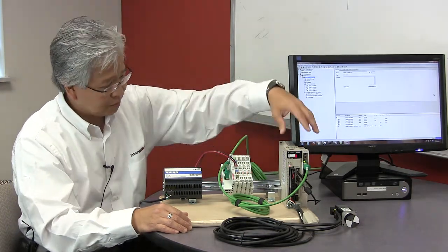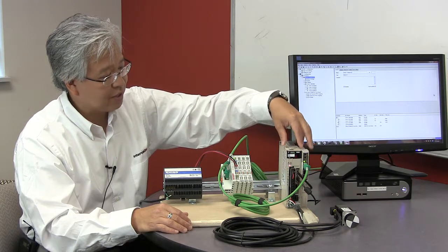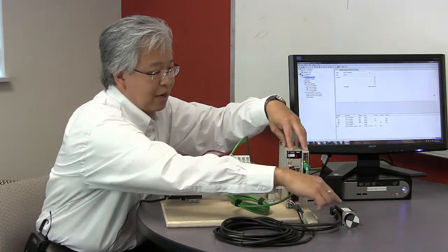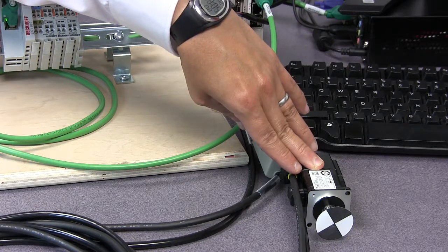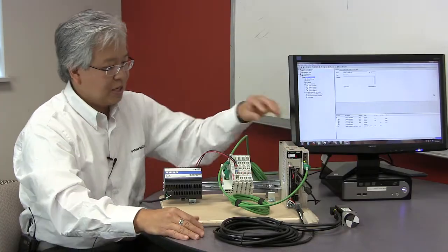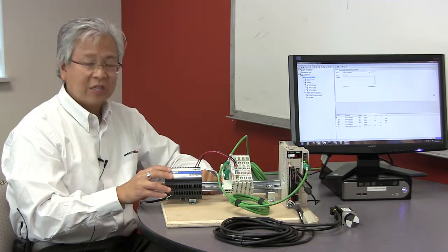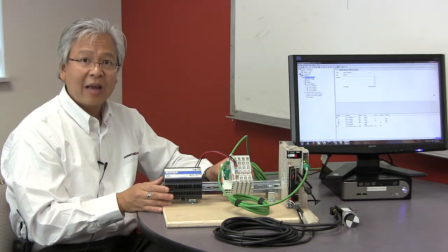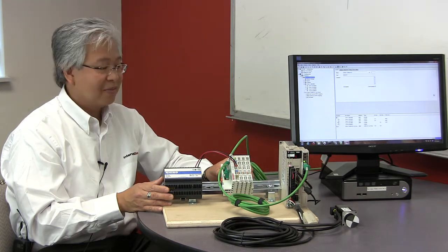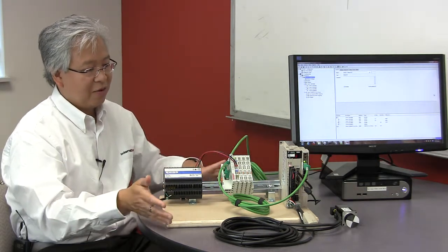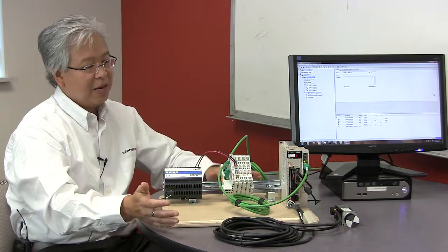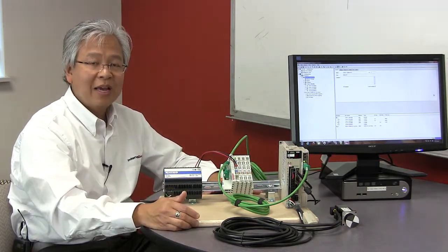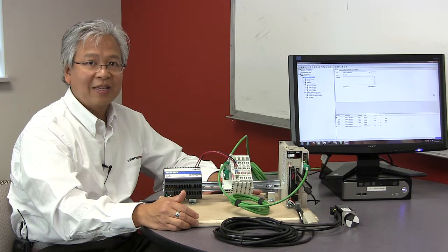Coming back to the drive, just finishing up here. Here's the Yaskawa drive, and then we have cabling coming down to our servo motor down there. Just finishing up, this is a 24-volt power supply, providing power to the EtherCAT modules here as well. So this is the full layout, and in a minute I'll talk about how we can get this motor spinning and running some of the canned demos that come with the SDKs.